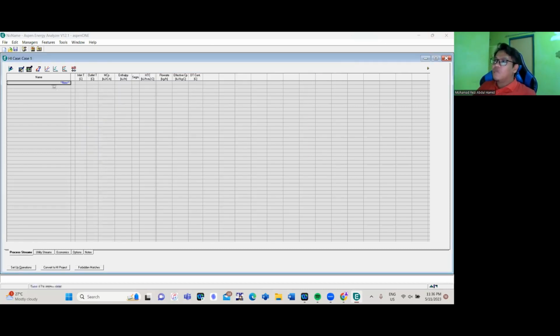All right, so first things first, as I said before, we need to specify our process stream. The first stream is a hot stream, so I'm going to name it H1. Okay, stream hot. Now, if you hit enter, it will go to the inlet temperature. Inlet temperature is 170. It needs to be cooled down from 170 to 60. You hit enter, it will go to the next column, 60.